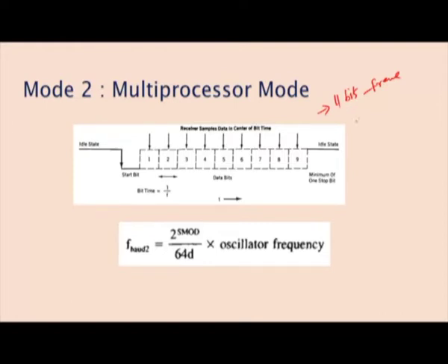Here 8 bits plus 1, the 9th bit is added. The 9th bit is what is represented in the SCON format as either RB8 or TB8, right. When that position is 1, it indicates that an interrupt has been received externally. Whenever an interrupt is received, it will be 1. If it is 0, it means no interrupt has been received.